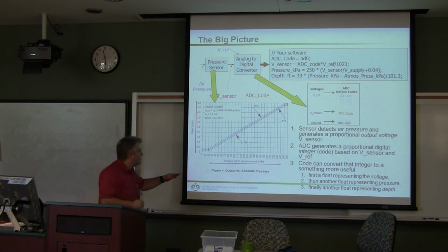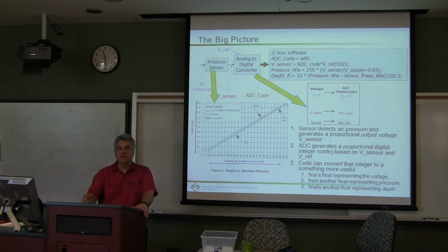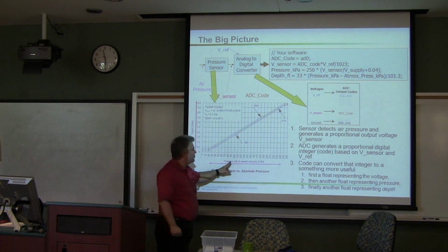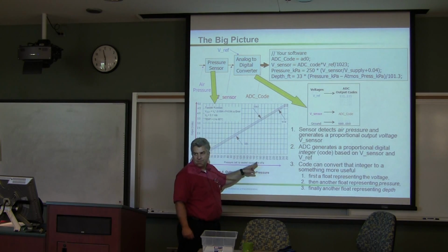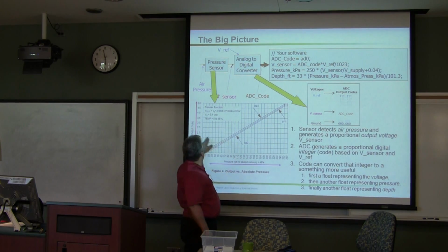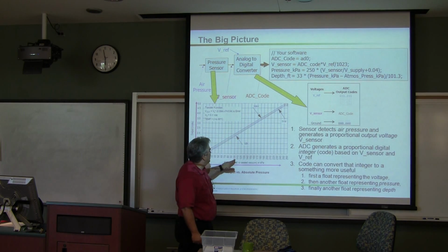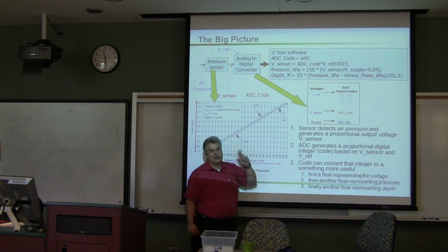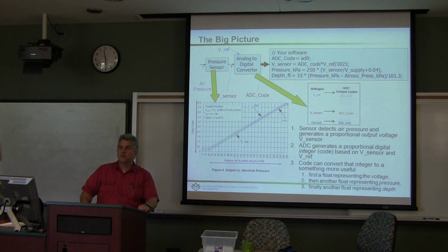For every sensor that you have, there is going to be some sort of curve that's going to tell you what your typical measurement is going to be. So, for example, depends on what your pressure is, and this is kPa, kilopascals. You will measure 2 volts if the kilopascals is approximately 100 based on a maximum possible temperature. So there will be some variance depending on what the temperature is of the actual measurement device.